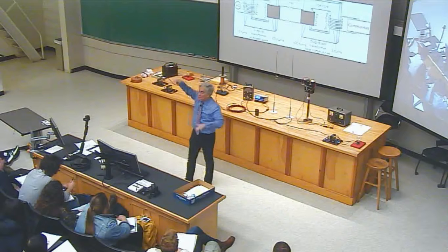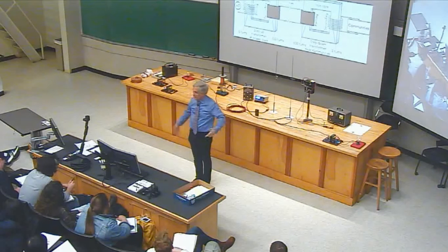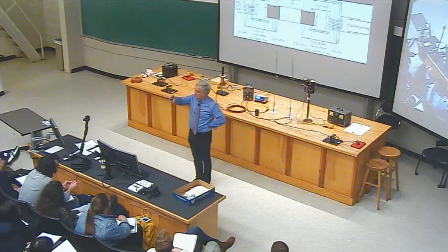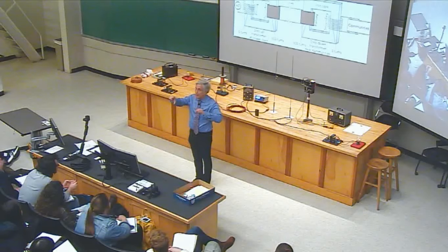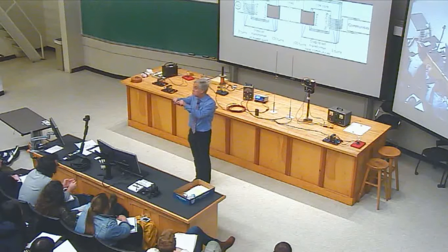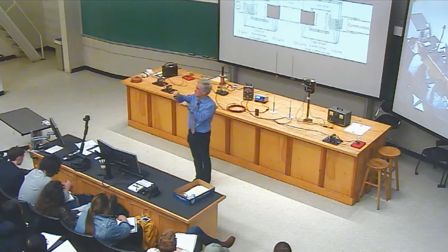So the power grid, your outlets that are nominally 120 volts AC, if you actually look at the voltage difference between those two wires, on a certain type of average, it's 120 volts. But at any given instant, it can be 0, and it can be as much as 170. It's actually bigger than 120 by a multiple of the square root of 2.